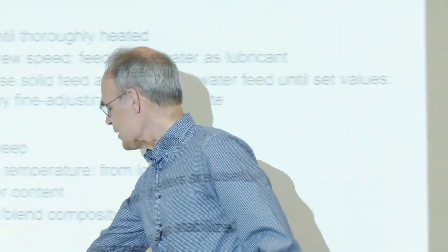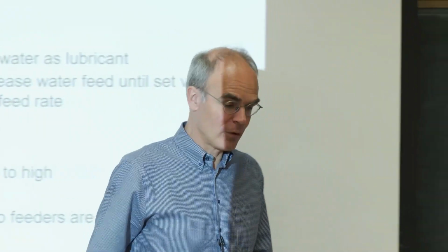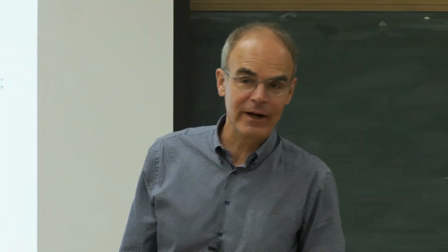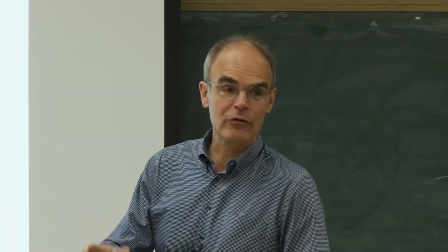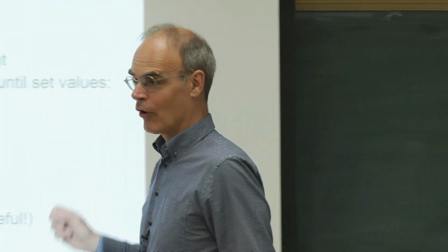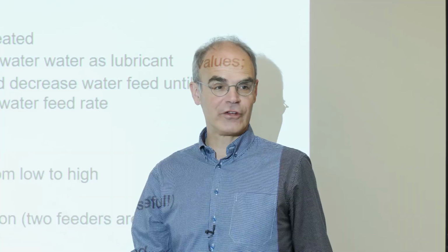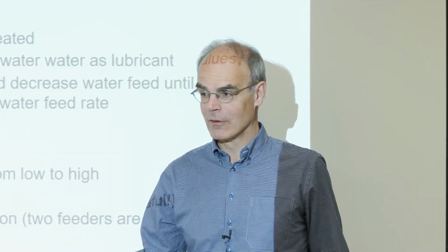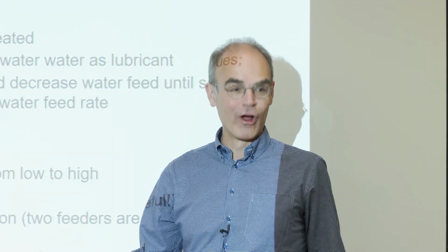So the thing is, if you ramp up water content, let's say if you do low moisture extrusion here at 160 degrees centigrade, also make sure that your temperature goes down. Now what happens if I put a lot of water at 160 degrees suddenly? What happens? There's going to be a lot of steam.